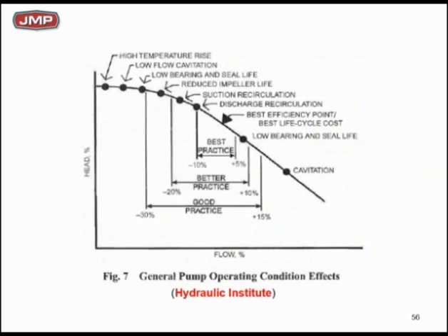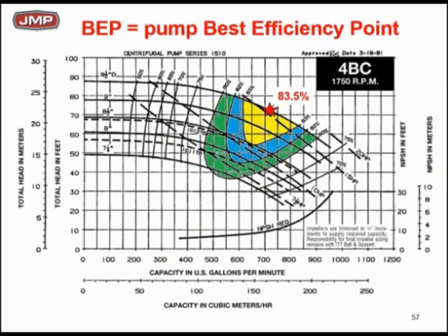You can dig a little deeper if you like. Just going to quote what HI does. Here's the best efficiency pump curve idea. This one's 83.5. Let's talk about efficiency islands real quick. We mentioned it. Everything in yellow there would have an efficiency island equal to 83 points or higher. Jumping on down to the green, everything in the green would have an efficiency island equal to what?